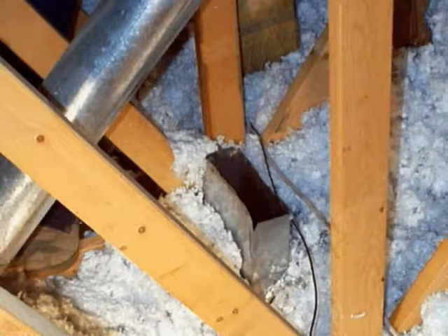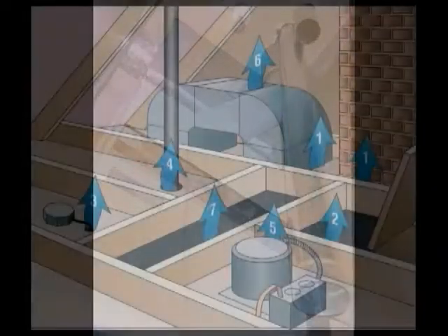So can combustion air intakes that come down from the attic through the house, if the heat from the house causes the air in the combustion air intake to rise into the attic. The normal passive combustion air openings are not one-way valves, and if a competing driving force stronger than the chimney draft wants to pull air out of the CAZ through them, it will.